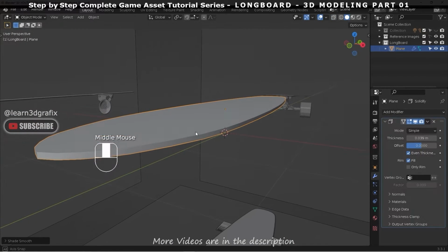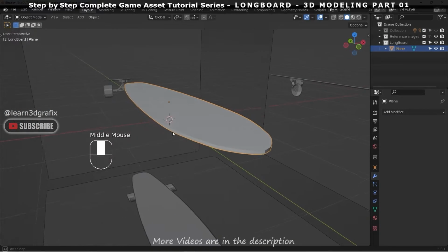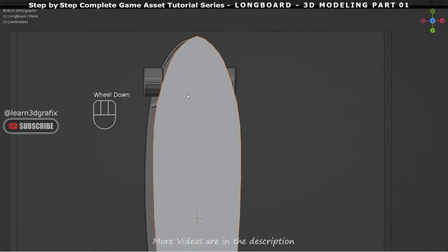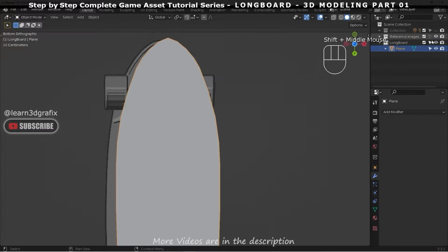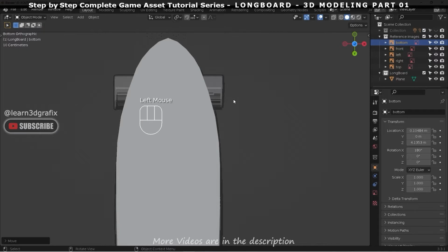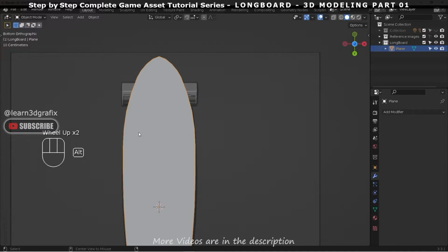If you are happy with the thickness, then apply the modifier. Now press Ctrl numpad 7 and go to bottom view. As you can see, our reference image is not matched with the plane. So we have to select the bottom reference image and move it to the center. Now freeze it again. Now select the plane. Press Alt Z to go to X-ray view.